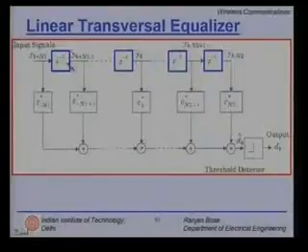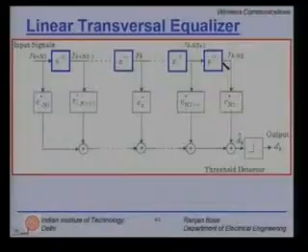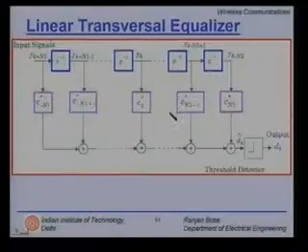Please note these are the tap points delayed by Ts, the symbol duration, and the number of delay elements would be a function of the delay spread of the channel. The weights are complex as shown here. These weights must be updated by some method.